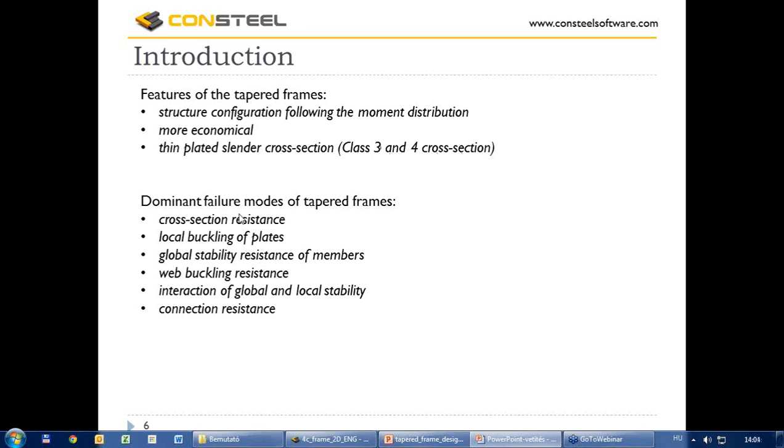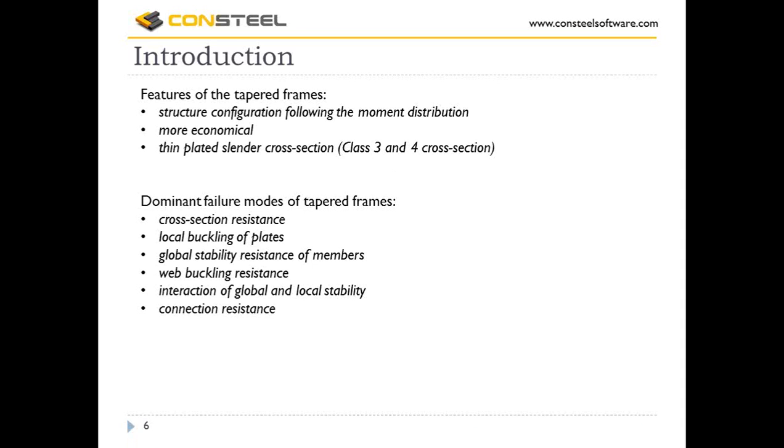What are the dominant failure modes of the frames? Cross-section resistance, local buckling of the plates, global stability resistance of the members, buckling resistance, interaction of global and local stability, and finally the connection resistance.